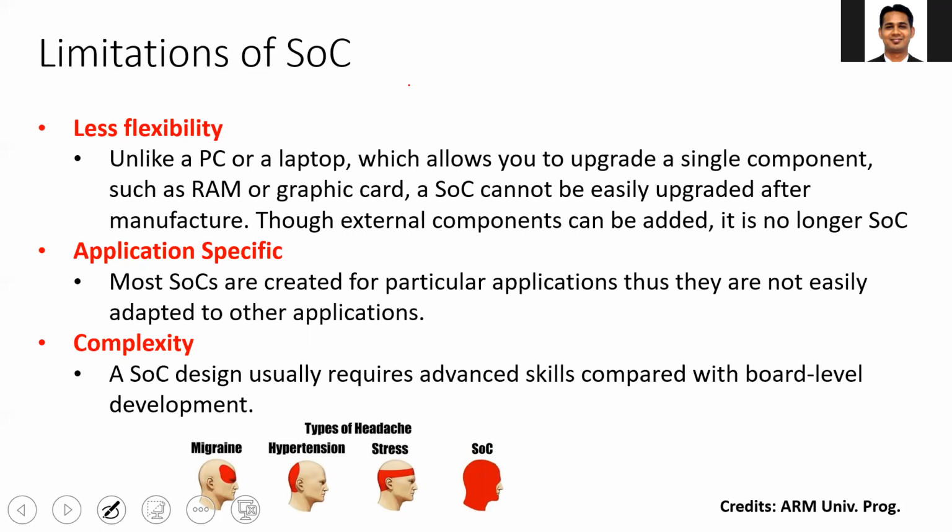Also, there is complexity. In a system on board, you can have different engineers working on different chips and one engineer at the PCB level. But when you are designing a system on chip, you need an engineer who has good knowledge about the various aspects of the system on chip. You can't separate out the work.